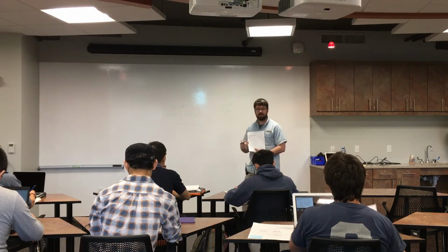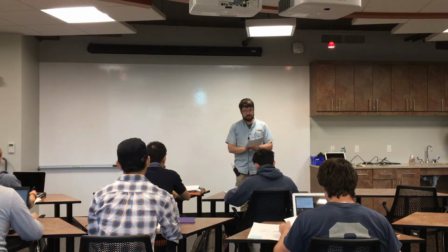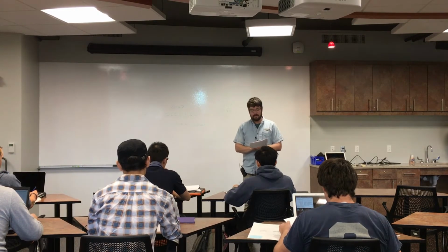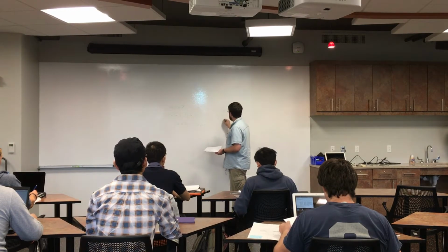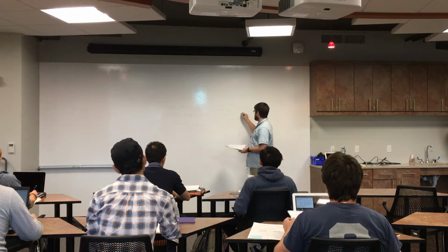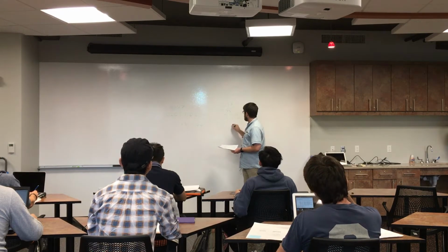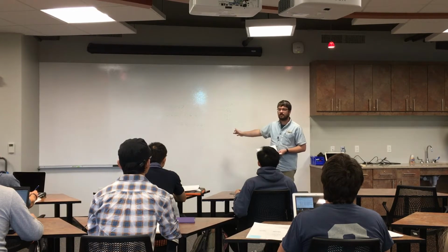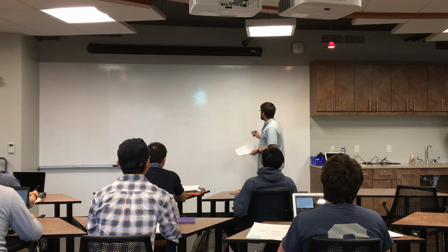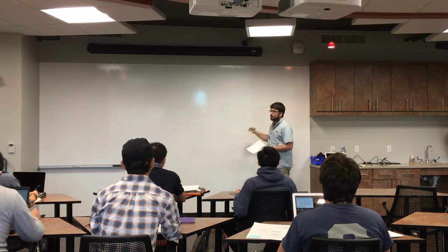So if you're looking at an oscilloscope or a logic analyzer, you're seeing a time series of ones and zeros. AA is 10, 10, 10, 10, and 55 is 01, 01, 01, 01. So you would just see a square wave with a 50% duty cycle. So that would be 1, the other one would be the complement of it. And you can do logic operations and do things like AND or OR those together and get very nice all zeros or all ones, right? So some people said, like 0xFF and 0x00.